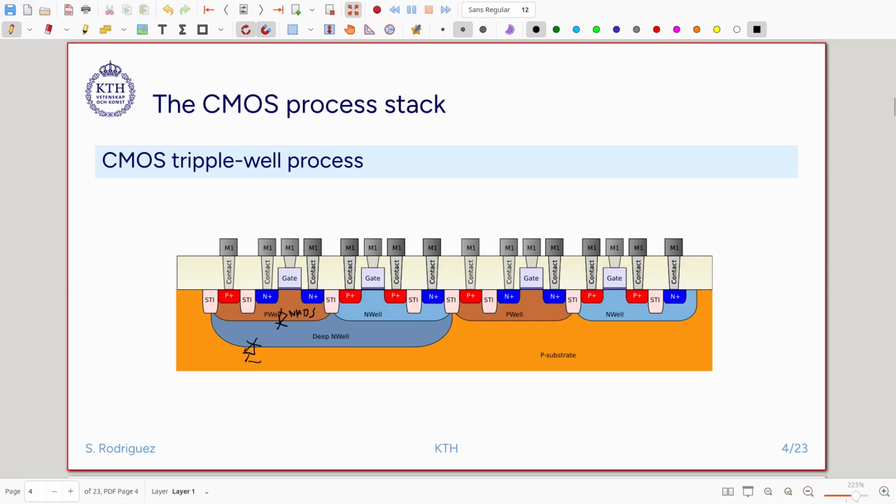Remember that at very high frequencies the diodes also have capacitance, and then they start short circuiting. But at relatively low frequencies we have complete isolation of the NMOS devices, and we can also put N-well devices. The N-well devices by definition are also isolated, no? They have an isolation